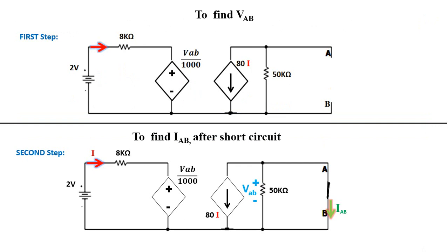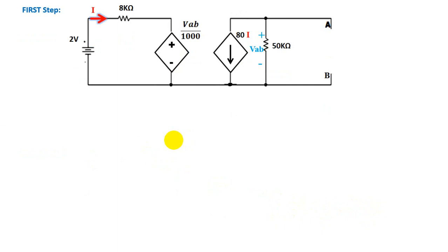As we are aware, we have two steps under Norton theorem or Thevenin theorem, and this comes under type 2 problems. So step 1, we will find VTH or VAB or VOC. Step 2, we will find IAB or ISC, right? So we can call this ISC. Under Norton theorem, we'll call IAB as IN, right? Now to find VOC, open it across AB.